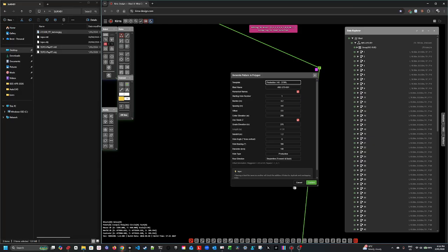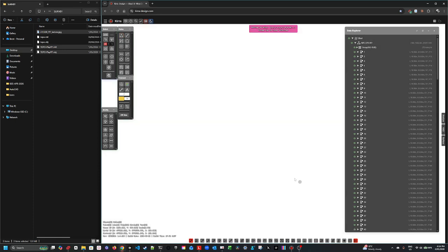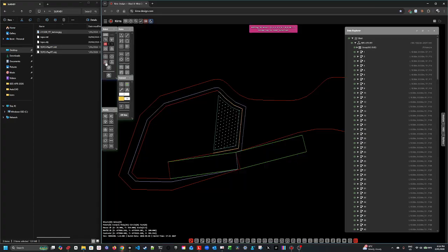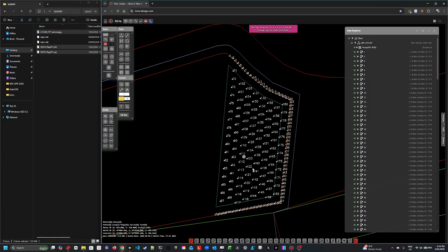All right. This has 1.2 subdrill. Okay, let's confirm that. Now it's gone bright white. Why? Because we're so close to the hole. So we're just going to zoom out. That's how close we were. All right, so now we have this pattern of blast holes in there, so that's good.